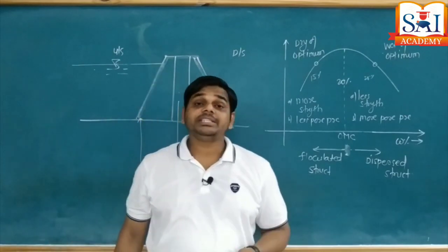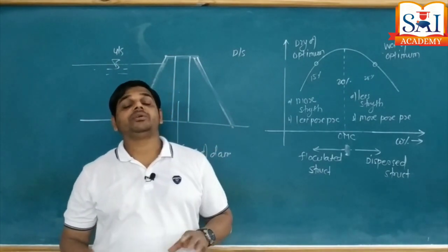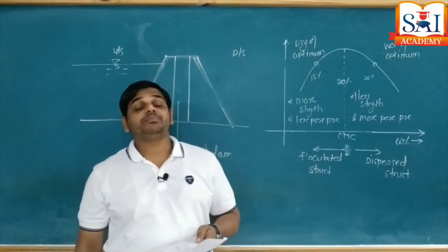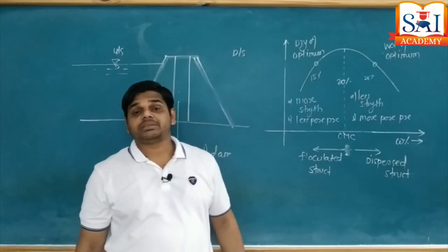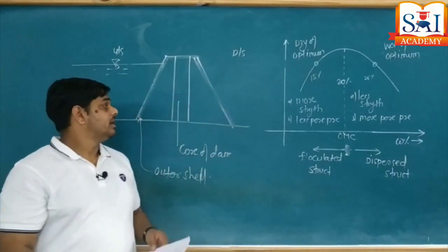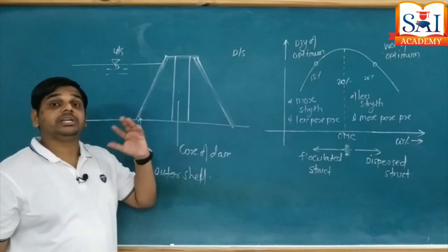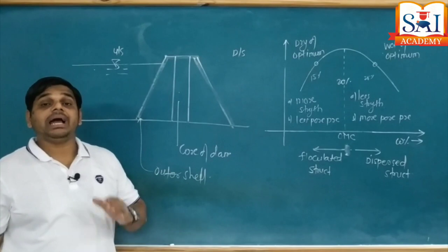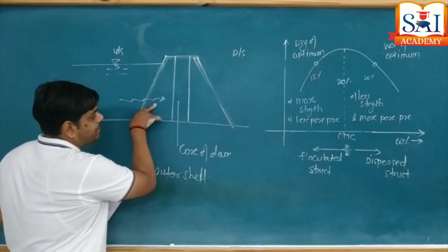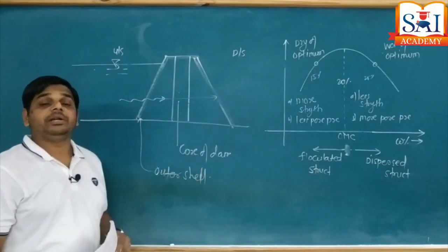To avoid large expansion and swelling pressure, soil is compacted to wet of optimum. म्हणजे ज्यावेळी आपल्याला swelling and expansion pressure कमी करायचं असतं, we are going to compact the soil to wet of optimum. असं कुठं लागतं? In the case of an earthen dam, at the time of construction of the core of dam. What is the core? It is made by a special type of soil. This soil totally avoids swelling and shrinkage, because when water seeps through the body of the dam and seepage occurs from upstream to downstream, when seepage reaches the downstream face, the stability of the dam reduces.